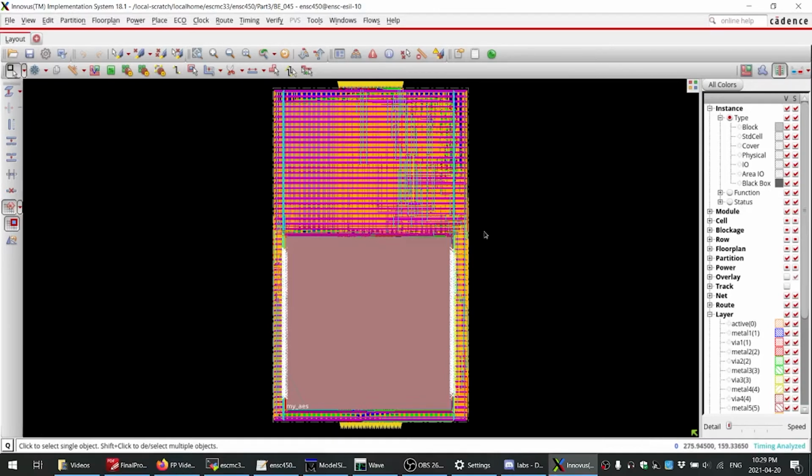And here's our SoC after the final backend synthesis, place and route. Since we had to use the AES core and the SRAM as hard macros, and they both are pretty square, we thought it best to manually define the dimensions of the chip to be rectangular.